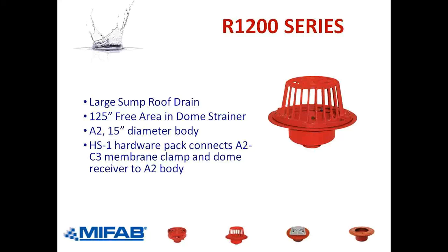Some of you, next time you look at the HS1 hardware packs in your warehouse, you'll notice that we made the diameter of the top flange of the bolt a little bit wider. We did that because some people said that when we bolt the A2C3 clamp ring to the body, we're not getting that much grip area from the underside of the bolt head pressing down onto the clamp ring, securing that ring to the body.